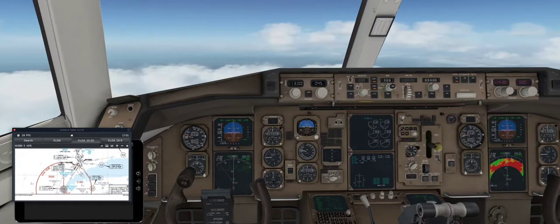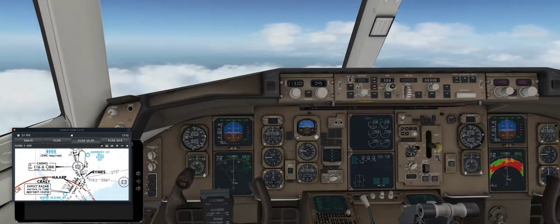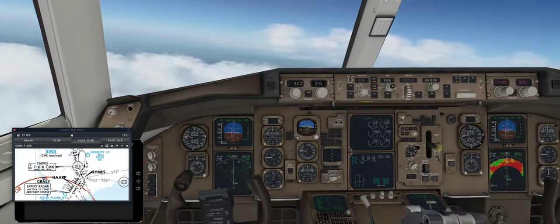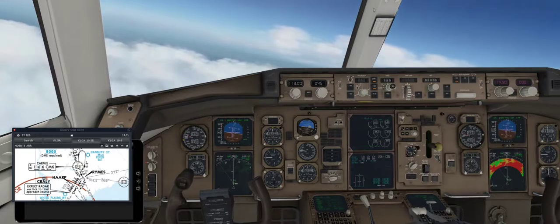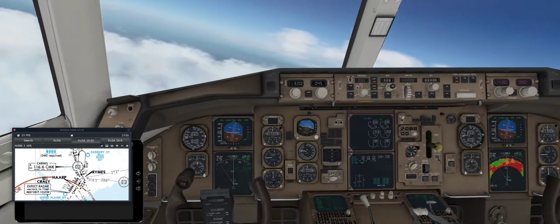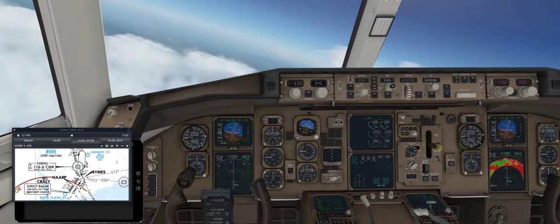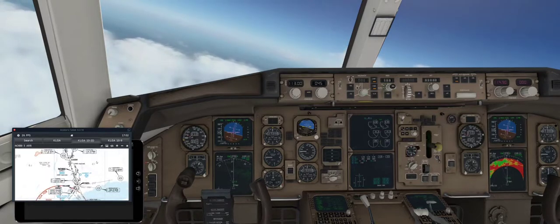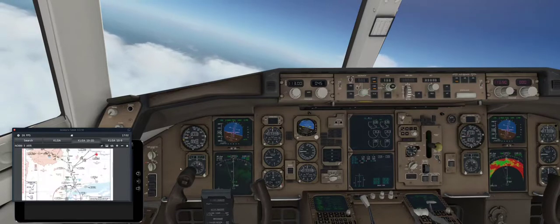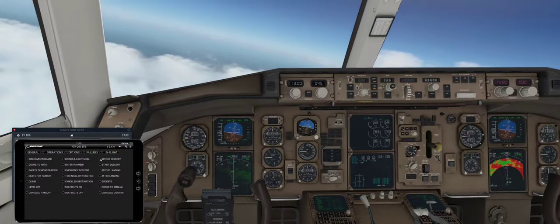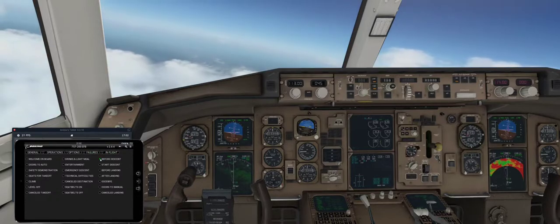And then you notice there's an altitude of 4,000 here. Between Rhymes and this one is 4,000, and then finally at the end of this approach we're supposed to be at 3,000. And by putting this, I'm going to put it all the way down to 3. I've given the system permission to descend as per that arrival all the way down to 3. And we're about to start descending, so we should probably button up the cabin and the people.